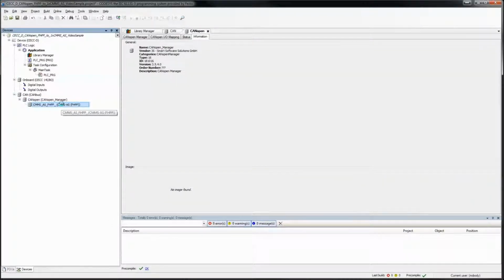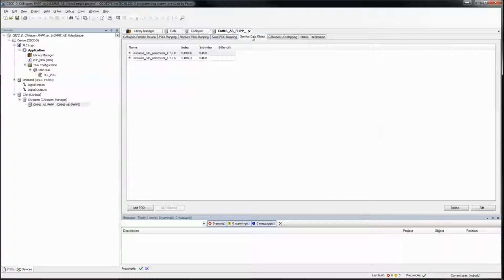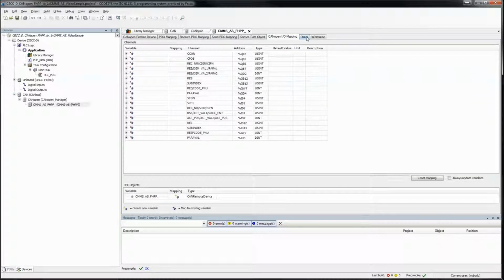Close it, open up this. I know that I'm going to set my node address to 3. Nothing else I'm going to change, okay? It's important to understand the starting addresses because the starting addresses of inputs and outputs, that's what we'll use later to map. So at this point we have a base value and we can start bringing in the library and start writing some code.